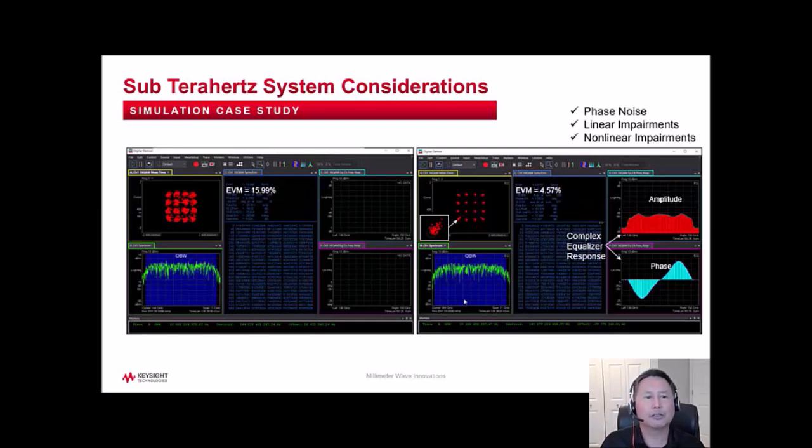After the adaptive equalizer is run, a diagonal pattern shows up in the constellation states. The pattern is a result of gain compression that is now present on the signal, and it shows how the adaptive equalizer corrects for linear impairments, but it doesn't correct for nonlinear impairments.